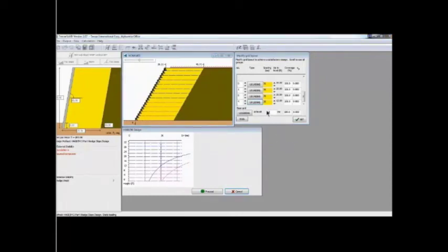We could have also changed the spacing of the geogrid. Instead of keeping them all at 36 inches, we could drop them down to 18-inch spacing, and you will see that now at 18-inch spacing, these points are still to the left of that spacing curve, so we're okay. And now we can jump up to 36-inch spacing at roughly elevation 12. So we can now add layers of geogrid up above.